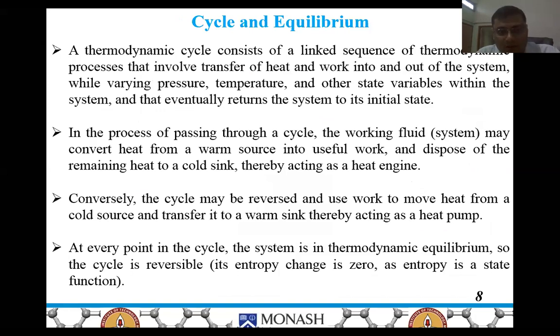Now, cycle and equilibrium. A thermodynamic cycle consists of a linked sequence of thermodynamic processes that involve transfer of heat and work into and out of the system while varying pressure, temperature, and other state variables within the system, and that eventually return the system to its initial state.